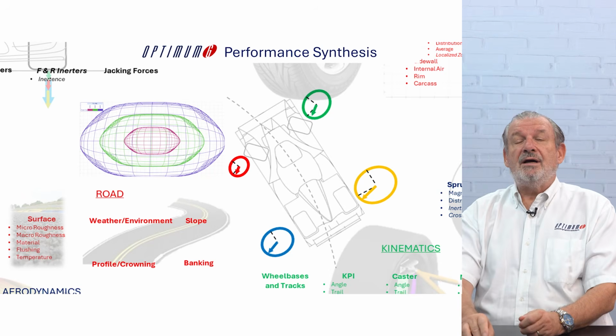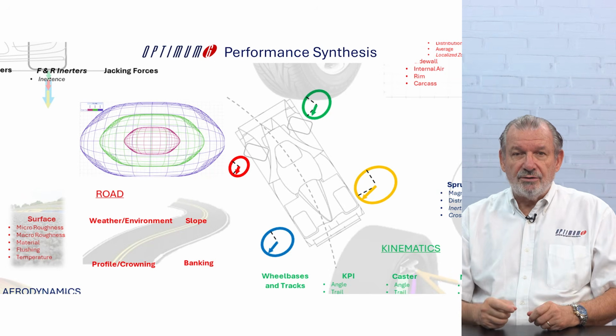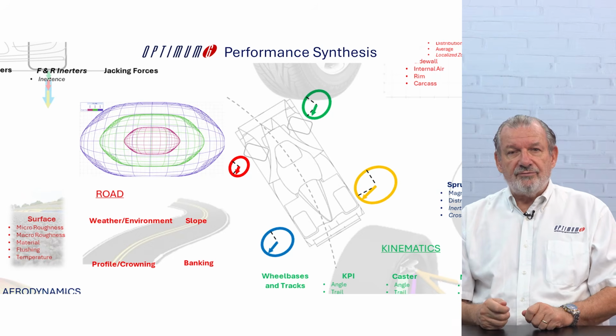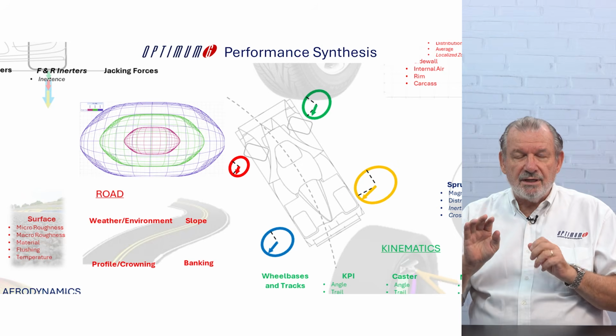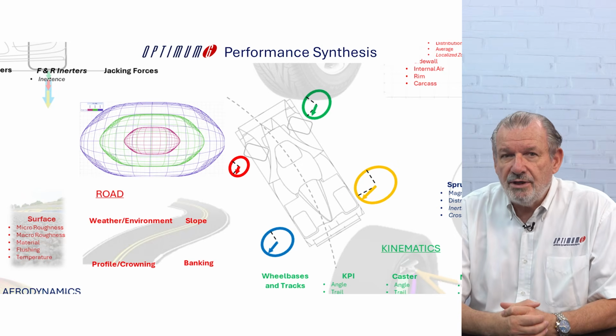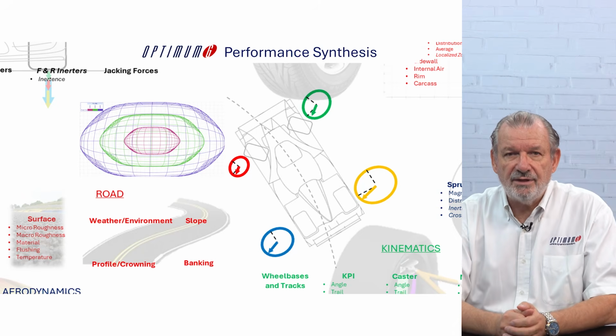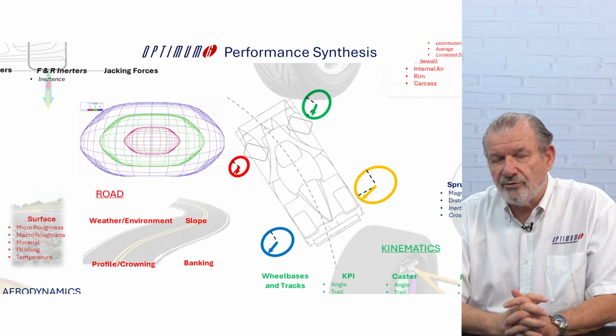And it's not only the response of the tire to the driver input: cornering, braking, throttle. It's also the way the tire is sending information back to the driver, and the ability of the driver to feel these forces and moments at the four tires at the same time. So understanding the tire on its own is a big chapter of vehicle dynamics. It's actually the longest chapter of our applied vehicle dynamics seminar. Personally, I'm not in love with tires more than I am with aerodynamics or kinematics or load transfer, but that's the reality. Everything is happening in these four contact patches.